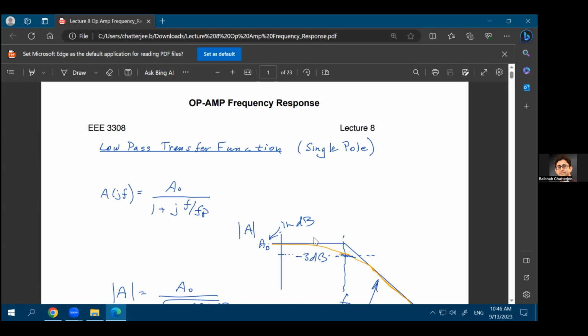Yeah, it's basically R2 divided by R1 plus R2. Same formula that you have learned in lecture number 1. So the formula is nothing different. It's just that you're taking the impedance of the capacitance instead of taking an impedance of a resistance. And impedance of a capacitance is 1 upon SC. And that comes from the Laplace transform equations, which we are not going to cover in this class. We're assuming that you have already covered it in your circuits 1 and circuits 2 class.